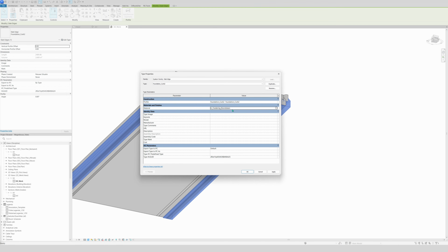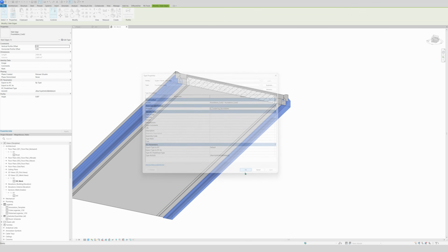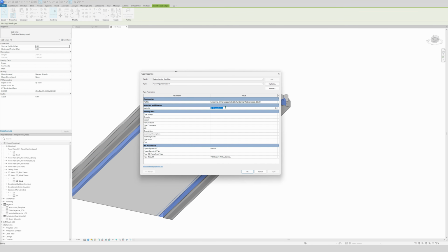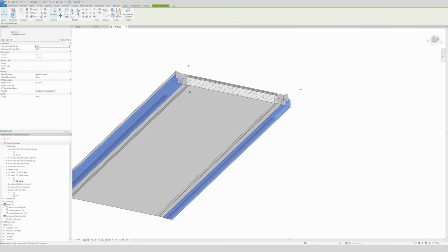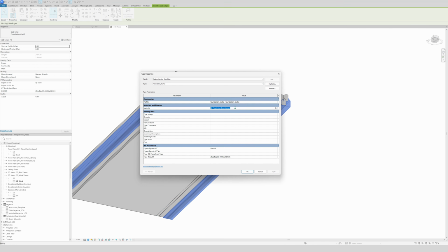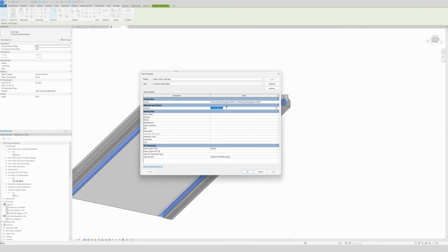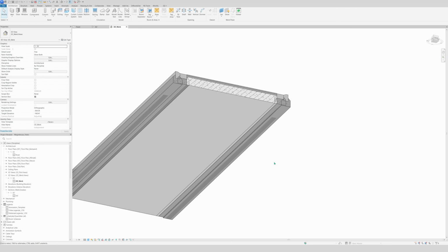There we go. Well, a little trick that you can do is just selecting here, Control C, apply, and then we go to the next one, edit type, and just do Control V if it works. Why? What have I done? Normally Control C, right? Okay, and then we do Control V. There it is, and apply. There we go. We have the same materials.